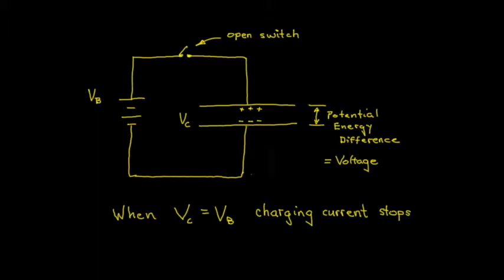This charge trapping approach can be a useful way of capturing or sampling a signal by charging up very small capacitors until the voltage between the plates matches the voltage on the signal source. Then breaking the circuit with the signal source allows us to hold the voltage equivalent to the signal at that moment in time. In a sense, this is a snapshot or sample of the voltage signal at that particular time. This is called a sample and hold technique and is frequently used to give us more time to measure and store the value of the signal.